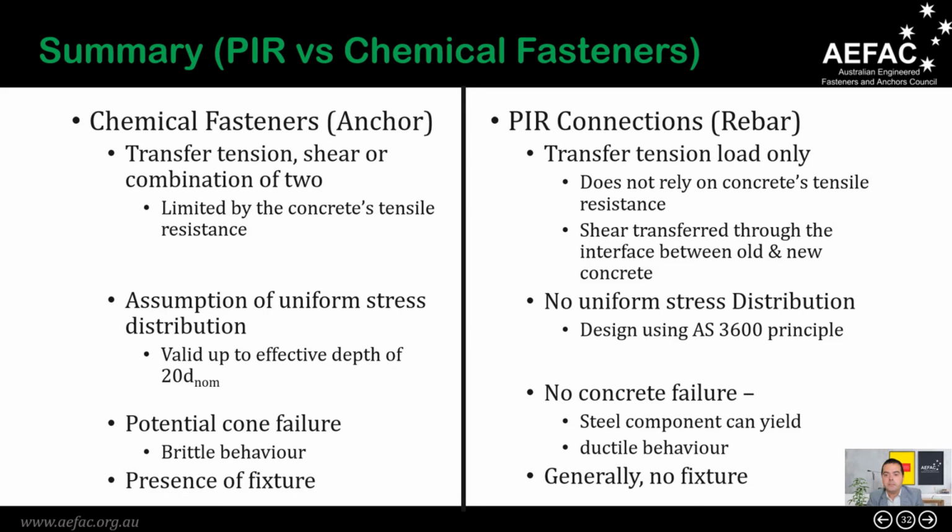The last difference is the presence of pre-stressing force from tightening the anchor bolts in order to clamp down the base plate, which is only typical to anchorage application, not in a rebar application. Based on those differences, the appropriate design method could be selected.